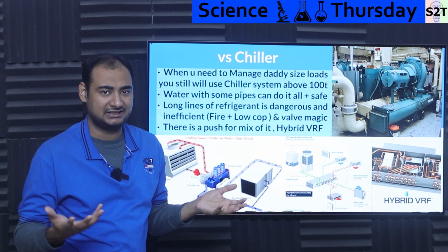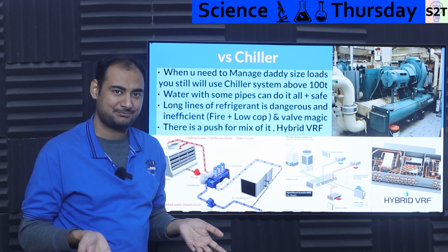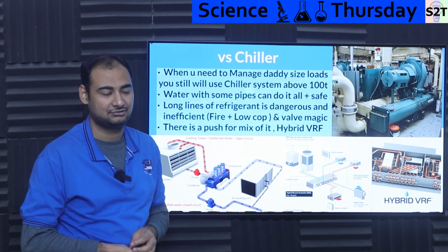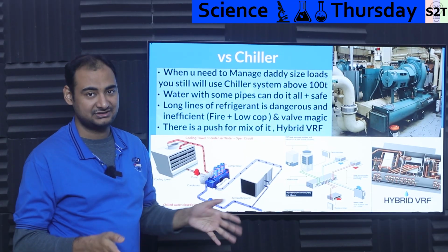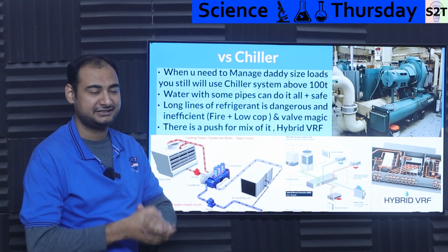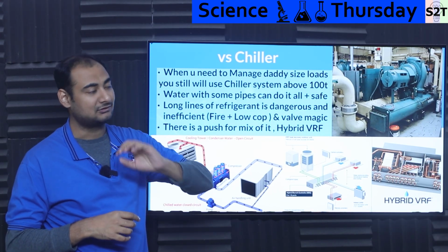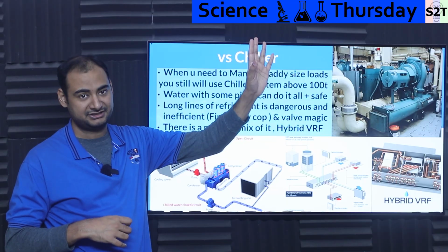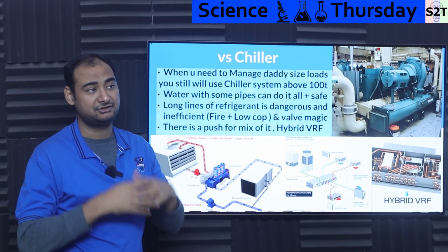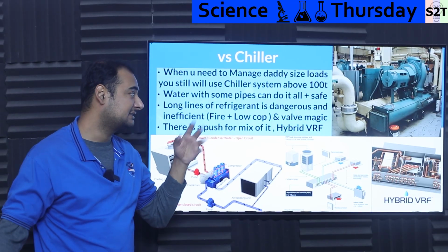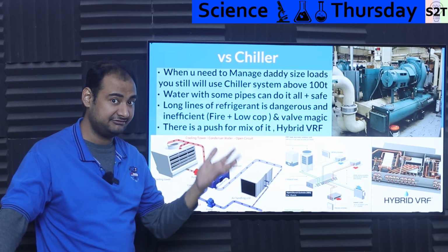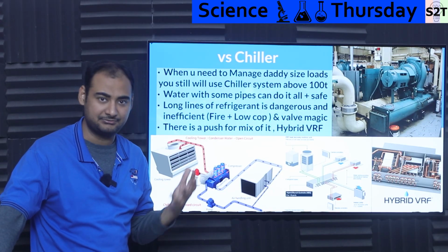We have district cooling, as in tens of kilometers of pipe or hundreds of kilometer pipe is like, bro, that's Wednesday for district cooling or heating. All of them are using water. Water is far more effective of carrying heat or cooling from one place to another, tens of kilometers. And again, if it leaks, not that big of an issue. Building catches on fire, not that big of an issue. So water has the ability to transport a lot of energy very far. That's the good part. Second, it's safe compared to refrigerants.